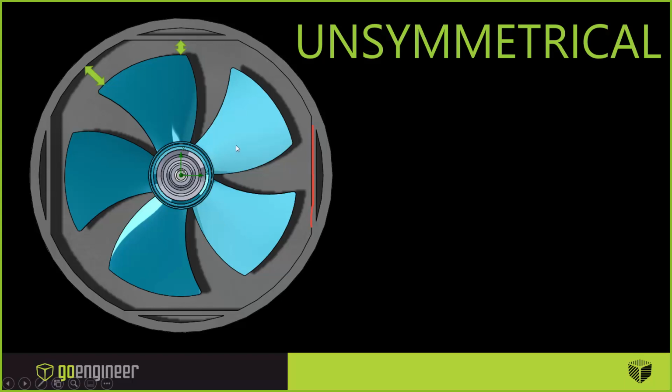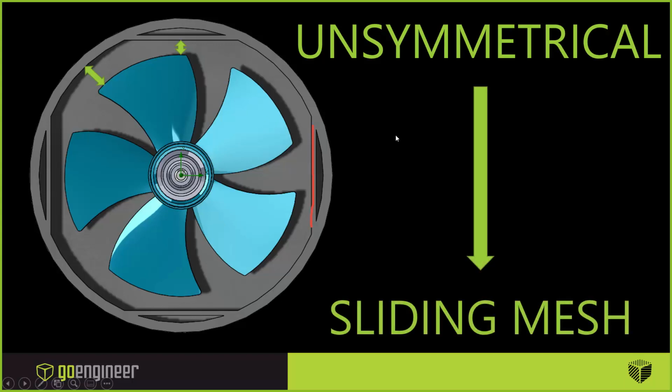It is highly recommended when I have an unsymmetrical region like this that I use the sliding mesh technique, where the mesh rotates at RPM instead. This way we are truly simulating the fan blades actually moving, essentially. And so we can capture the effect that they'd have as they move past the ribs. This is a much more accurate way to simulate the fan blades, but it does take a longer time to solve. So I'm going to teach you guys some speed techniques as you do this for your early design iterations.